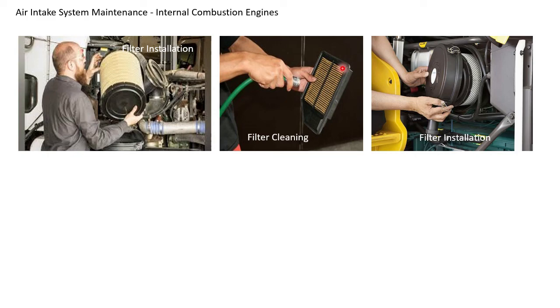Once the cleaning is done, you have to carefully install, place this filter element, checking this gasket. This side and this side there will be a gasket which is going and touching this filter housing. Ensure this gasket is clean, neat, there is no damage, and also on the housing surface there is no dent. Place the filter element and again pull this cap.